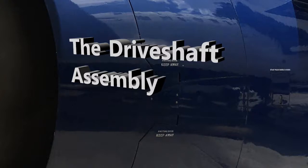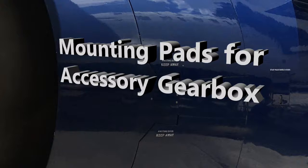So what do you have with the AGB? As far as the mounting pads that exist there, what are they for? You have mounting pads for things like the hydraulic pump, the IDG, the alternator, and the power supply for FADEC.